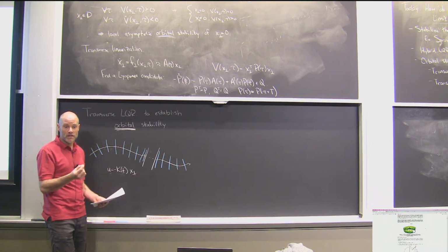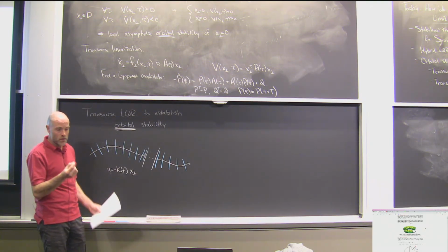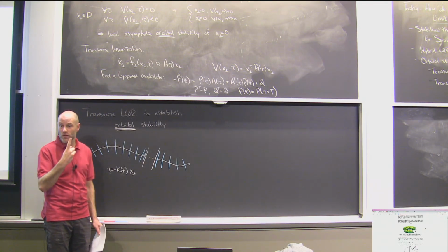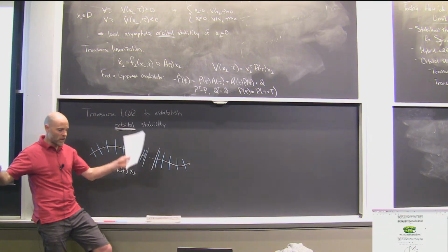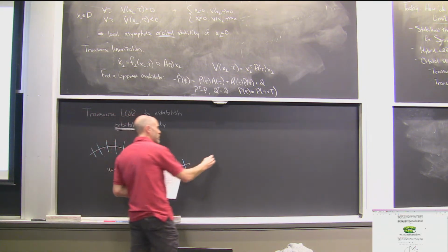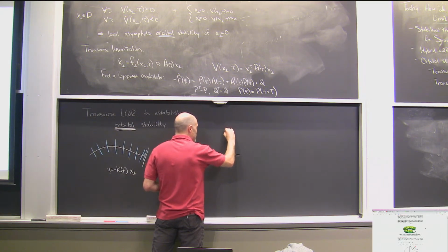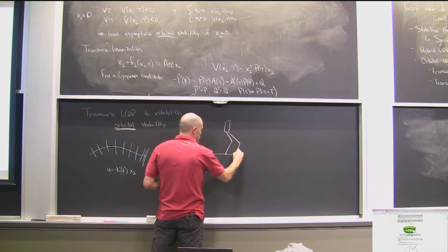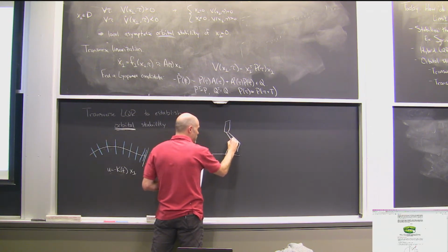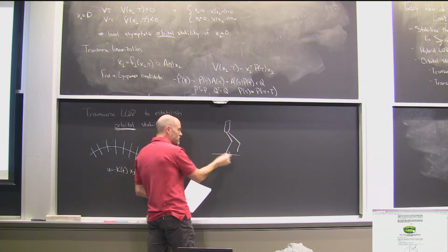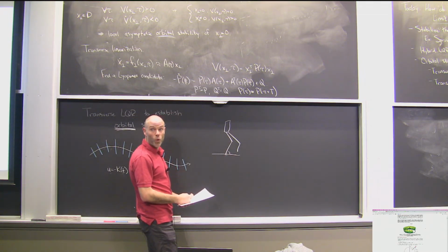And in the limit, there's an important limit where your walking robot, for instance, has underactuation degree 1. So you could have a large, complicated walking robot, but if you have actuators at all of the joints, except for maybe you've got a point foot, you could argue in the plane that that's underactuation degree 1.